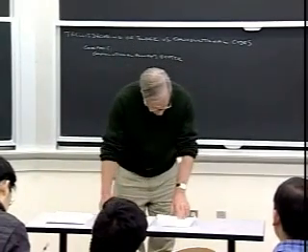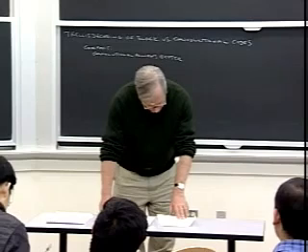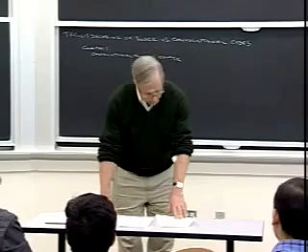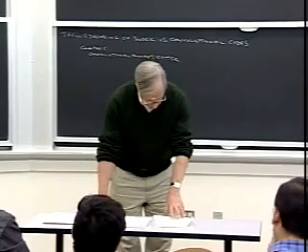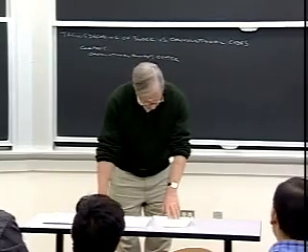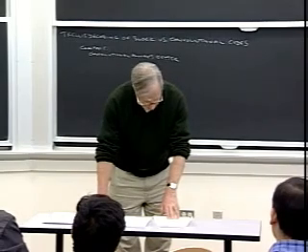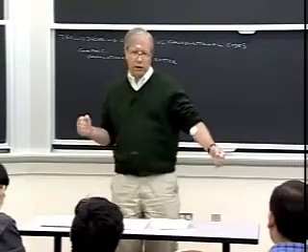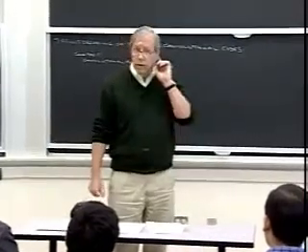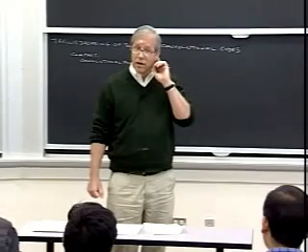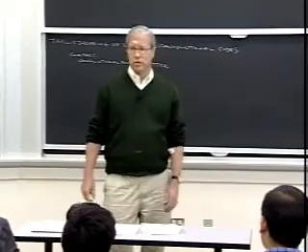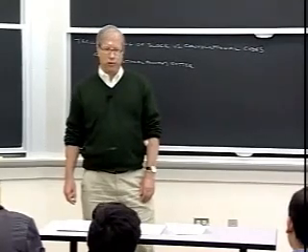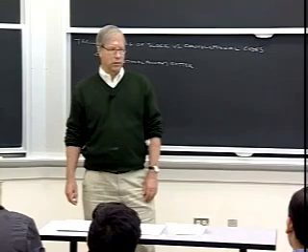All right. Another head-to-head comparison might be with the (32,16,8) Reed-Muller code. That's a rate 1/2 code. It's a very good one. It's known to be the best with those parameters, n, k, d. So what's its nominal coding gain? Anyone? It has rate 1/2, minimum distance 8. Its nominal coding gain is? Hello? 6 dB. You take the rate times the minimum distance, 1/2 times 8, you get 4. So that's the nominal coding gain. Factor of 4, which in dB terms is 6 dB.